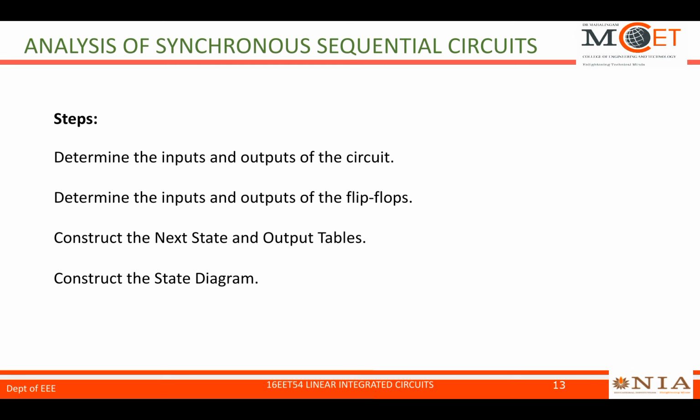Next we will see the analysis part of synchronous sequential circuits. These are the steps to be followed in analyzing a synchronous sequential circuit. First we determine the inputs and outputs of the circuit from the given state equation, state diagram, or circuit diagram.